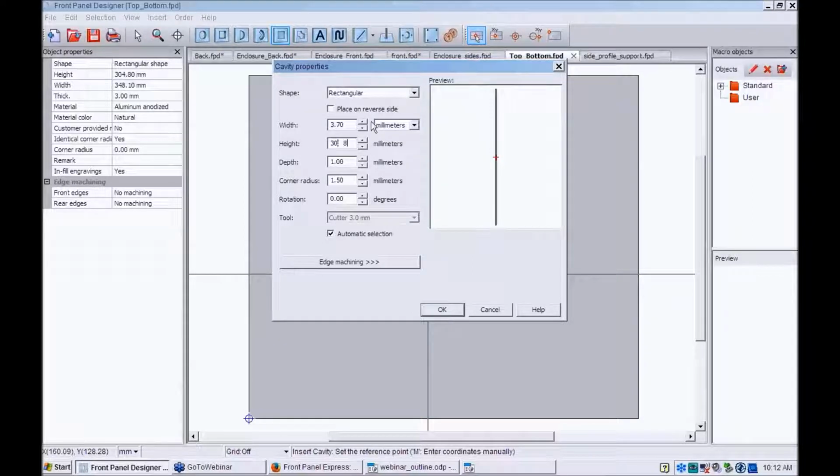Notice that we've made it 3 millimeters longer than the height of the panel. This is to allow for a clean edge and no burrs on the panel. We'll give it a depth of 1.5. Since we've selected 3 millimeters, and as I mentioned before, the cavity or the profile slot is 1.6, we need to get that material to 1.5 millimeters so it can slide into that profile.